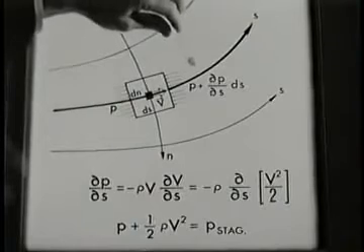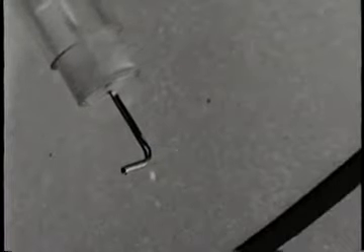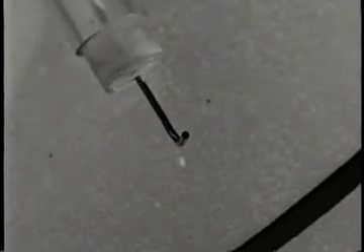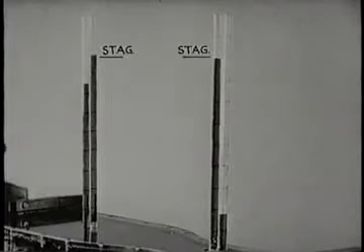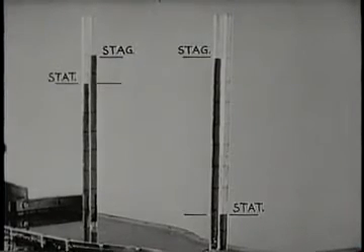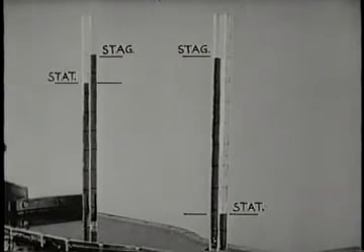The stagnation point is put to practical use in a pitot tube. The hole at the nose measures the stagnation pressure of the particular streamline reaching the hole. We've placed pitot tubes at the upstream and downstream cross-sections of the contraction, and these are the static pressure manometers we had before.